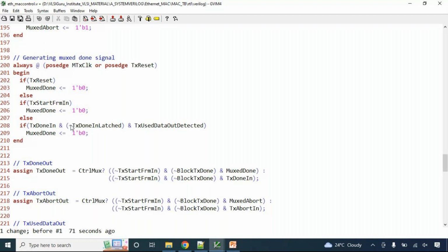Now you may say, what is the problem? Okay, what happens if it got missed out? What happens is this mistake, or I will call it a bug, goes into gate level code. Because when you synthesize, you know there is something called synthesis. What synthesis does is this Verilog code is converted into gate level format, and gate, or gate, and gate. That process is called synthesis. So during synthesis, this code is converted into gate level format. Now whatever mistake is there in the gate level code, it will finally get into the chip.